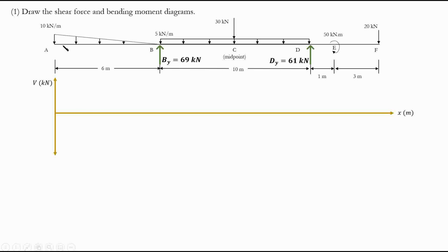And then we don't have any points here. So at point B, we have to know what the shear is just to the left of support B at this point, right? How do we know that? We can look at our diagram and say, okay, what is the change in load? At point A, the shear is 0, right? But what is the change in load from A to B, right? Basically, we can remember this, that the area under the loading diagram represents the change in shear.